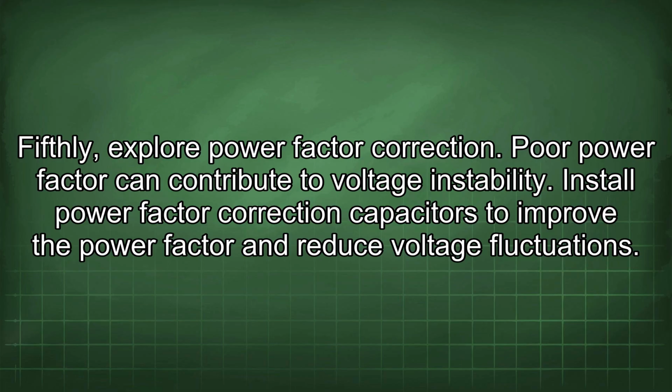Fifthly, explore power factor correction. Poor power factor can contribute to voltage instability. Install power factor correction capacitors to improve the power factor and reduce voltage fluctuation.